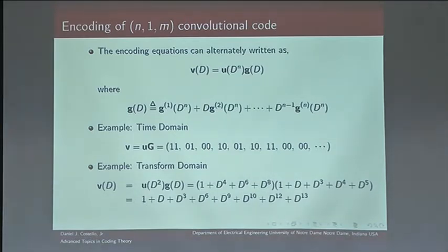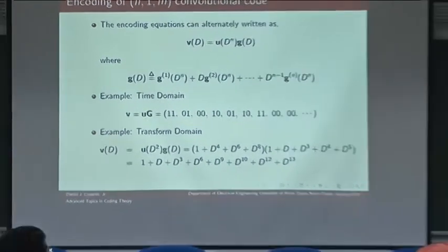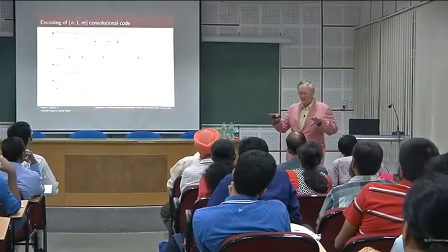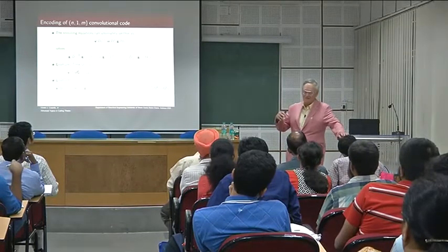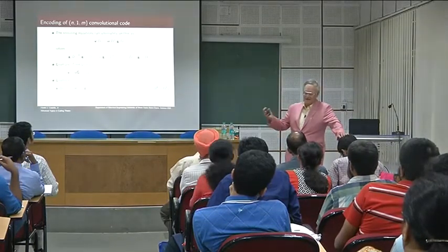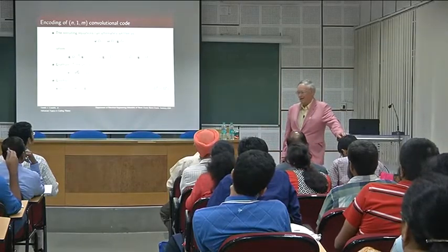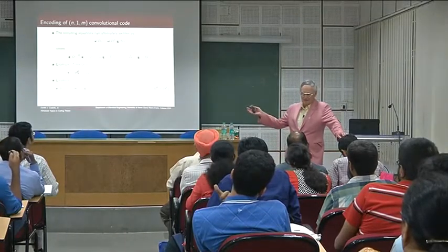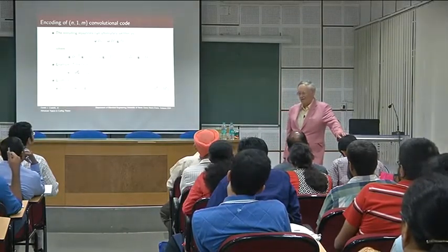Convolutional code with convolution, and then they want to relate that to block codes, where we also have this matrix form, so they want to show that. I don't know what other people do, but the reason I did it is because these are convolutional codes, so these are linear systems. These are linear time invariant systems. And so you want to get the whole linear systems analogy between convolutional encoders and linear systems, using both the time domain and the transform domain.